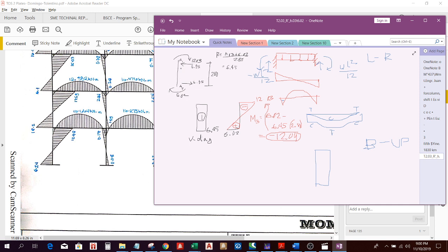Simply when you rotate this into a beam, this going to the right will simply mean going downward. That's it. So negative area for the shear. Like here, it's going up, so it's a positive area on the shear.